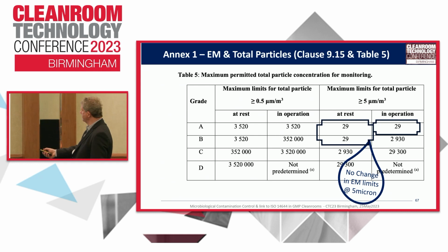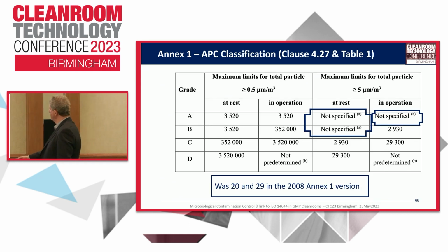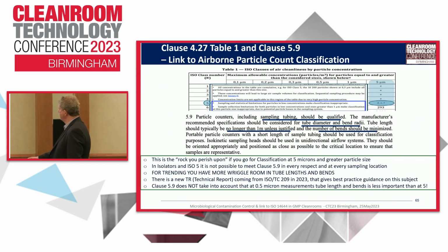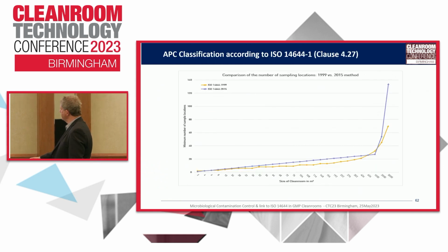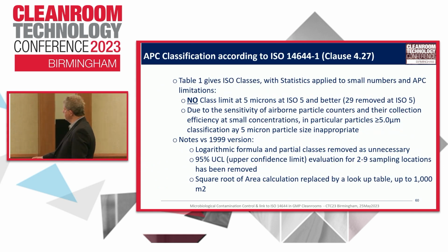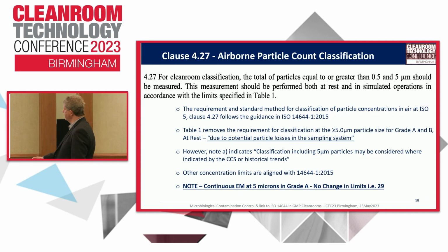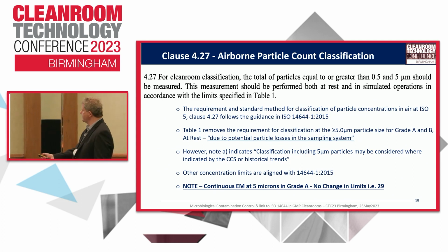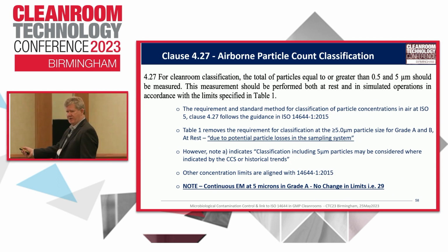Let's go back to here, if I can. Sorry, forgive me, I want to just go back to this. Sorry, I'm taking too long. Oh, come on. Sorry, I've got to go back here. But 14644-1 says for clean room classification, okay? Classification not the same as monitoring. You classify clean rooms because you can measure them, you monitor with microorganisms, right, okay? So you measure 5 microns, okay? That's where the confusion starts coming in, right?